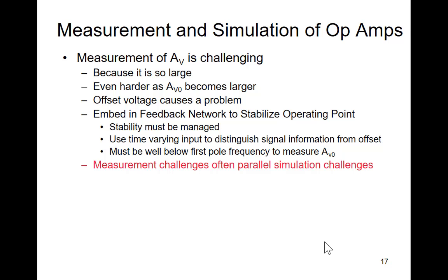So your second pole actually is out here someplace. We've neglected that. That's so that your phase plot will drop to a stable. That's correct. If you don't have this, you will either be unstable or you'll be underdamped. If it dropped here and beta was 1, it'll be unstable. If it drops about here and beta is equal to 1, it'll probably be underdamped.